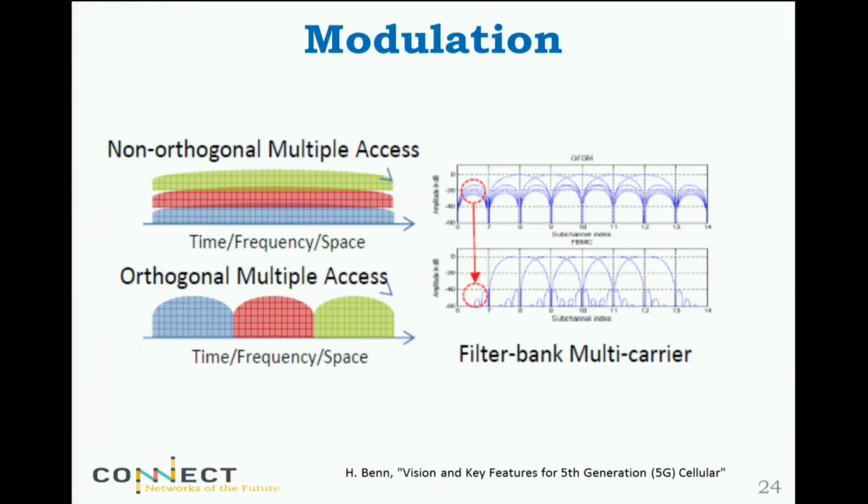With the cyclic prefix, first of all, you're wasting spectral efficiency, because some of your transmission time is not used for useful data transmission, though it has good properties against ISI and enables an easy way to convolve in frequency the signal and the channel. In essence, it's not a useful part of your frame. So they try to cope with that, either limiting the time you use for your guard time, or removing it altogether.